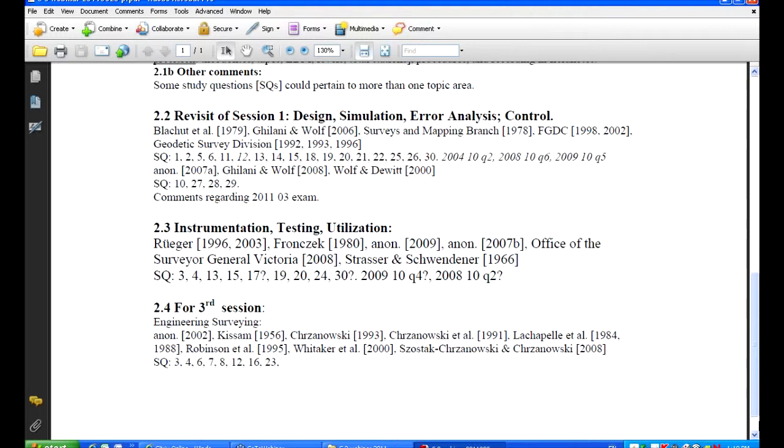The calibration baselines were created, and they were usually measured by the Geodetic Survey of Canada or some other higher authority to give knowledge of the distances, and they were typically 6 or 7 pillars. Because we had knowledge of the distances, we could then also calculate the scale of the EDM, in addition to doing the additive constant and getting some of these other statistical information about the instrument's behavior.